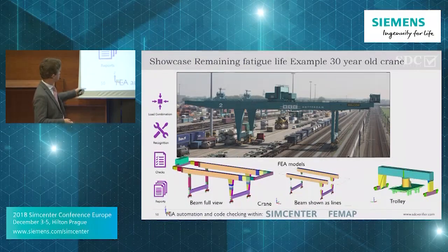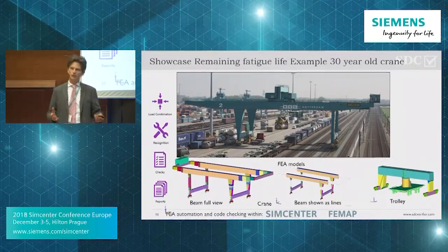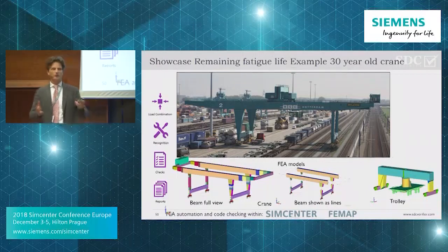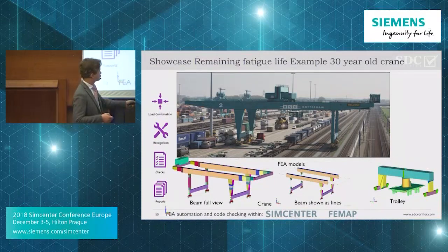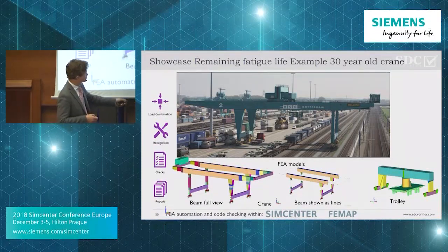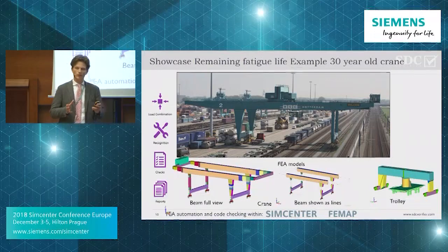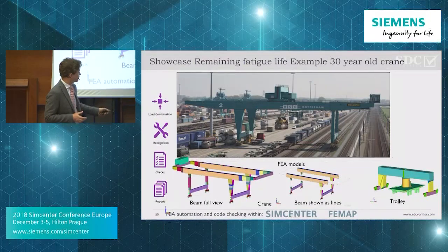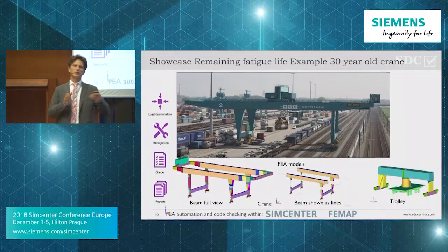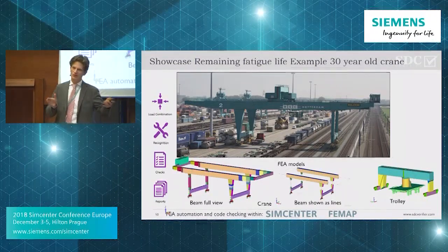We set up first with the beam model, just to get a quick overview. Where do we need to put extra effort in making detailed results? Then you see everything which is of interest or where we think that the beam approach is invalid. For example, any connection, so connections all over here, but also here in the middle, where it looks completely like a beam, but the load is asymmetric.